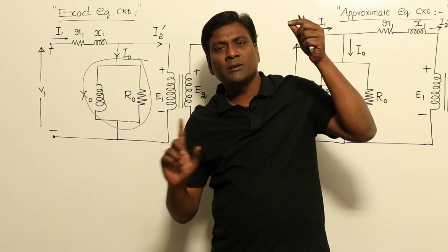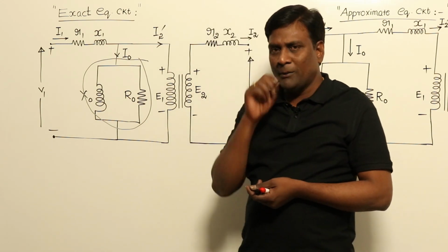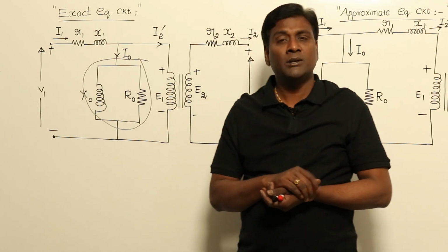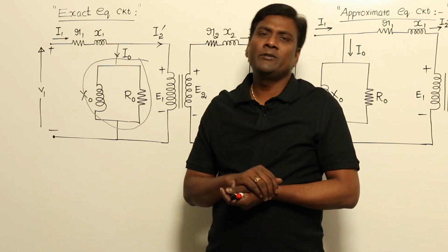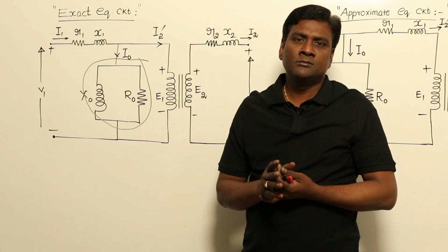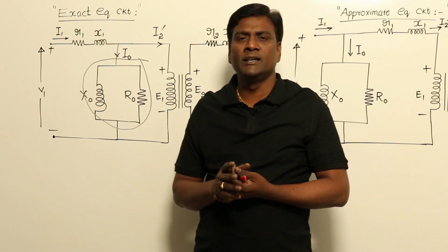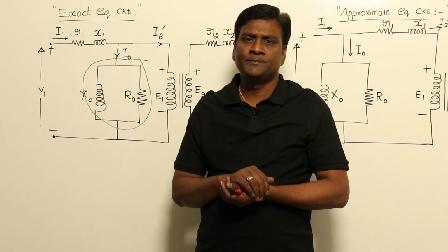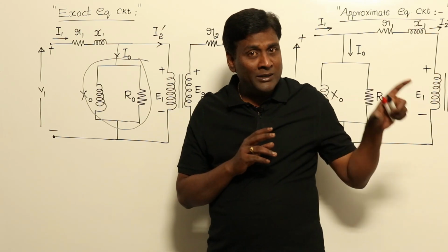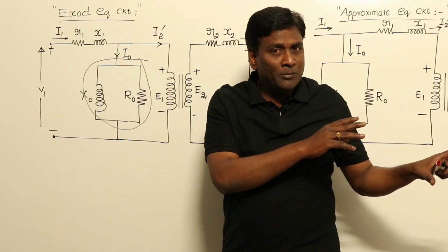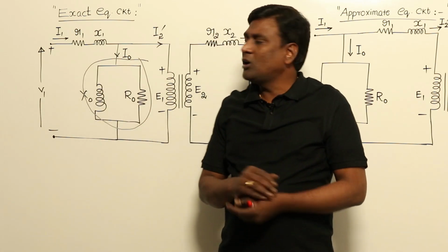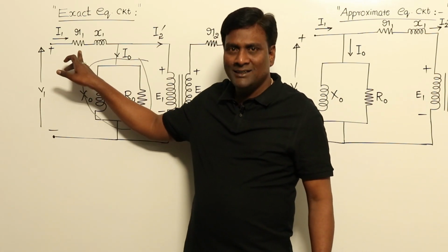Through this winding, if some currents are flowing, so through copper wire some currents are flowing, which is having some resistivity and area of cross section of copper and length of copper. So definitely some resistance will be there. So depending upon the magnitude of resistance of the copper winding, definitely copper losses will be there. Okay, so in order to model those copper losses, actually copper losses are happening in a practical transformer. Those copper losses we are trying to model on paper. Okay, so on paper we have to model with that resistance only.